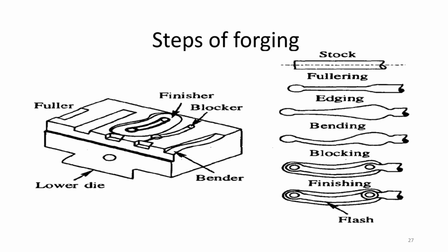Okay, ma'am. So it will be on that alloying diagram that two curves will be coming. Yeah, and also if you have a very high nickel amount, then your entire phase diagram will be changing. You'll have a lot of austenite even up to room temperature. The same if you have manganese at higher amounts.